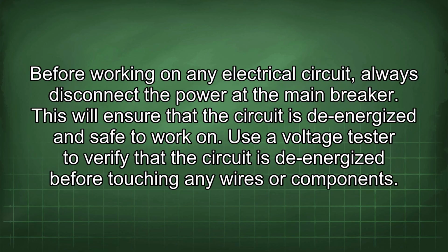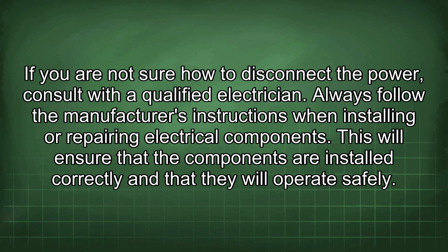Before working on any electrical circuit, always disconnect the power at the main breaker. This will ensure that the circuit is de-energized and safe to work on. Use a voltage tester to verify that the circuit is de-energized before touching any wires or components. If you are not sure how to disconnect the power, consult with a qualified electrician.